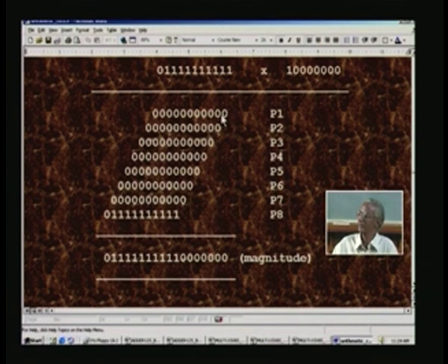What we have to do for the rest of the number is take the entire thing, bifurcate it by 2 and call it LSB and MSB, and then add at the first clock only the LSB, and then at the following clock we will add the MSB as we had done before in the adder case, and we will follow the very same pattern here, and at every stage it is going to be the same.